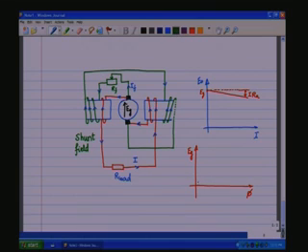This has a curve which goes like that and then droops, because there is no change in the flux, further it saturates. This is a function of IF. So, E naught is equal to EG minus I RA.